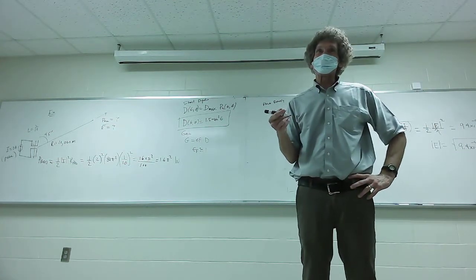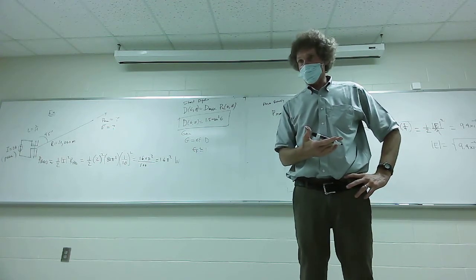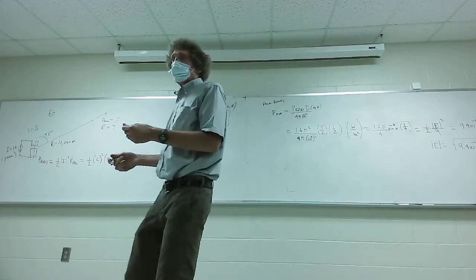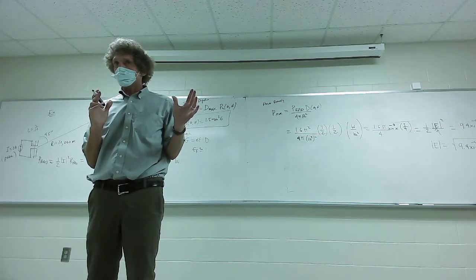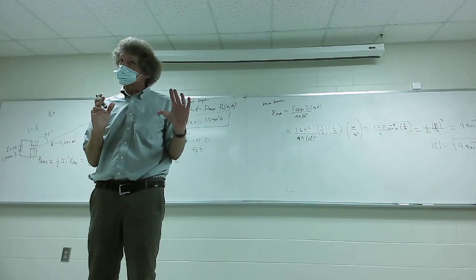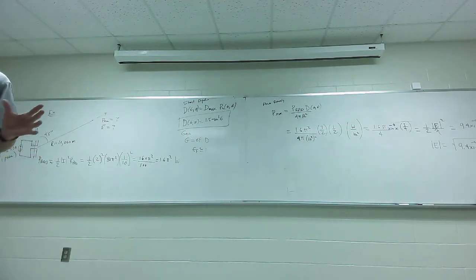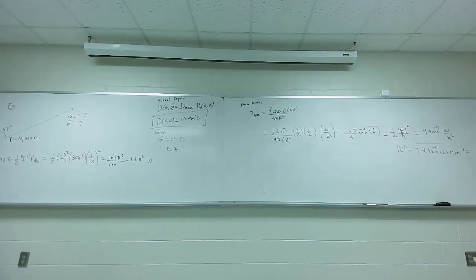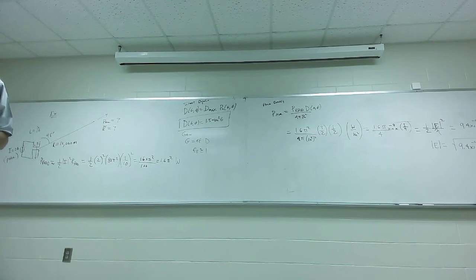I'm trying my best to get through this without driving you nuts, but I wanted to do an example, because then you see the benefit of knowing the gain of the antenna. Once you have the radiation resistance, or really the impedance of the antenna, some antennas do have an imaginary part that you can't calculate from the radiation resistance. Once you have that, if you apply voltage, you get the current. Once you get the current, you know the radiation resistance, you get the power radiated. Once you get that, you know the gain. In all antennas when you buy one, it will have the directivity and gain plots. So you will have that in front of you. It is a big selling point.